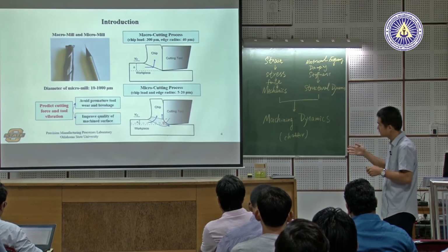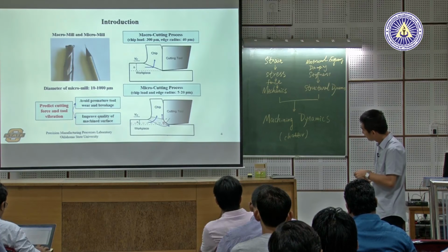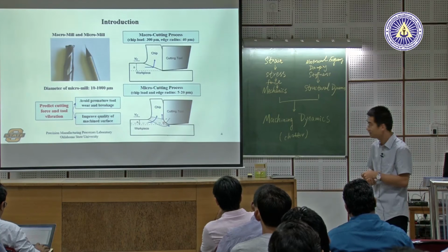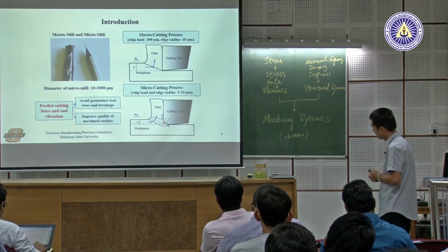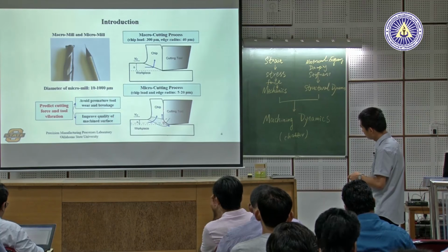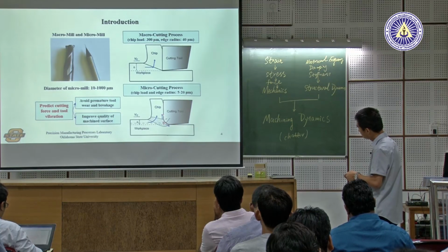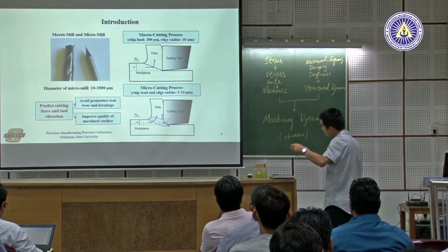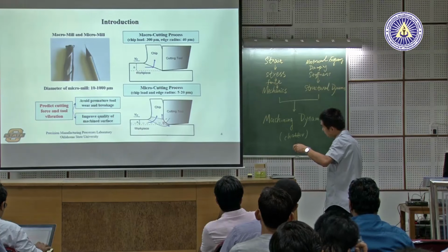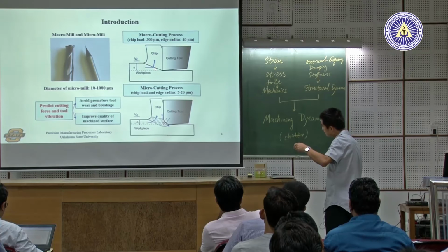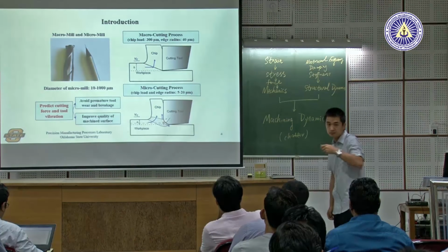But for our case, especially for my own research, we are mainly focusing on the edge radius effect. Okay, so that will be the main part. So now let's say we have the round edge of the cutting tool to remove this material. If the tool is super sharp here, we can assume the material suddenly deforms from its original formation to the chip, right? Just at this thin layer. Even with a sharp edge it's actually a small band, but for simplicity we neglect the thickness and treat it as just a plane.